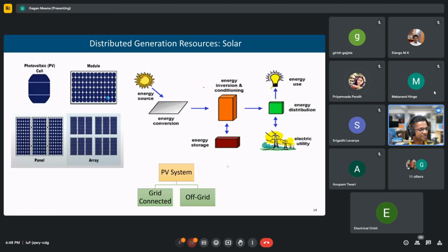Remember that although the inverter may have the capability, it also depends upon the grid codes. The grid code should also allow them to provide 100% reactive power. Technically it is possible, but whether it is allowed from the grid code and compliance point of view changes from region to region.